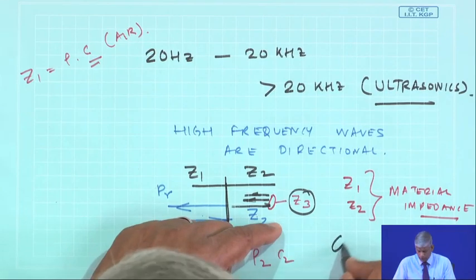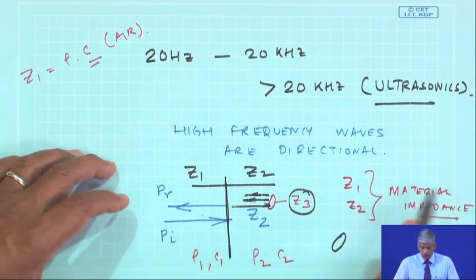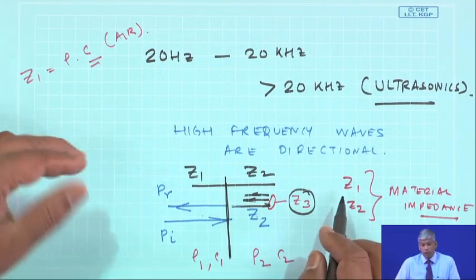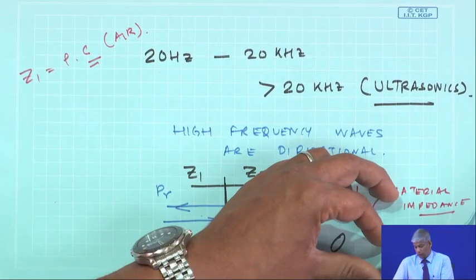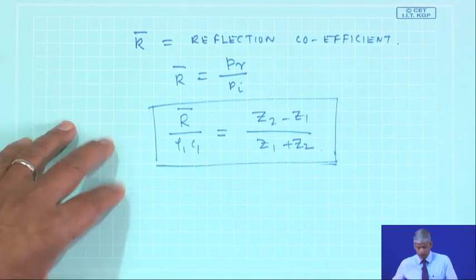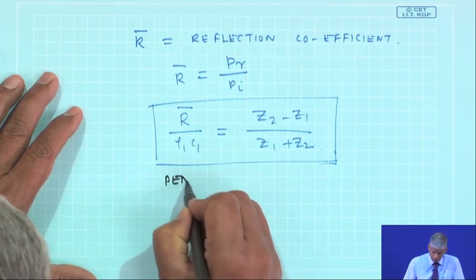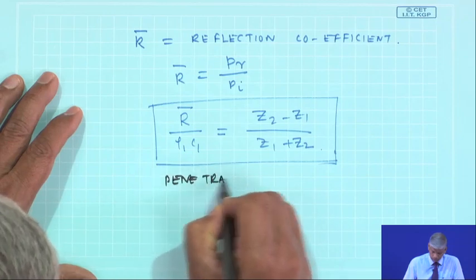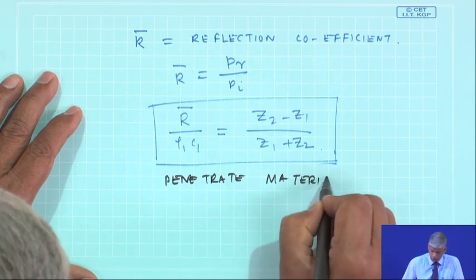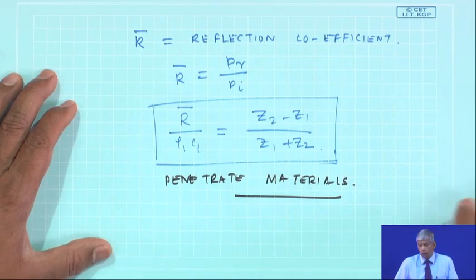It could be a void, it could be an air gap, it could be some crack. So, these are very helpful. Ultrasonic waves can penetrate into the material, because they are high frequencies, they have a lot of energy, and then we can use them to penetrate materials. Of course, the power would be very high, but nevertheless we can use them to find out.